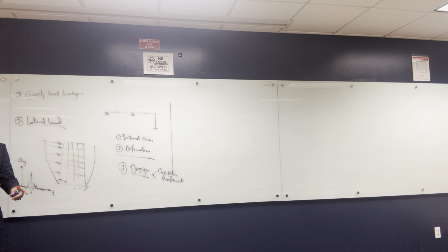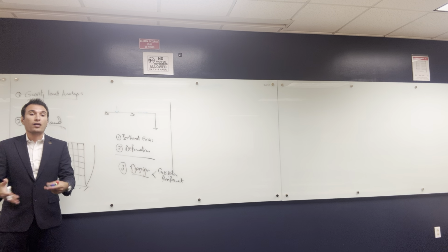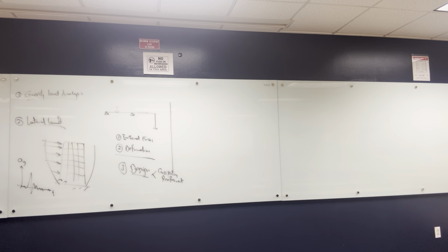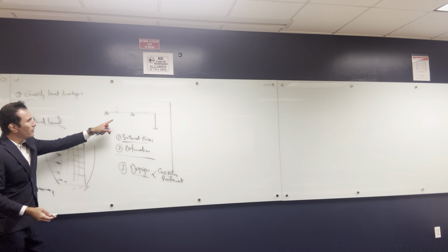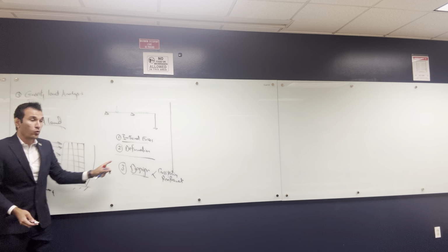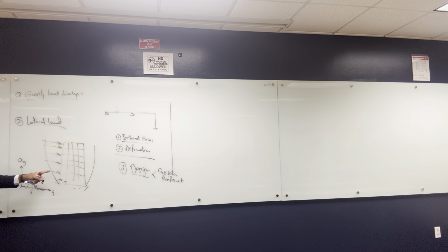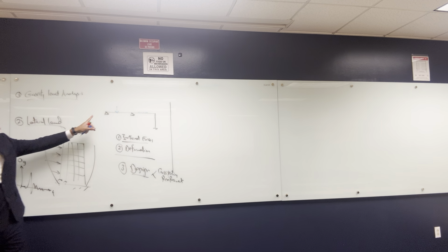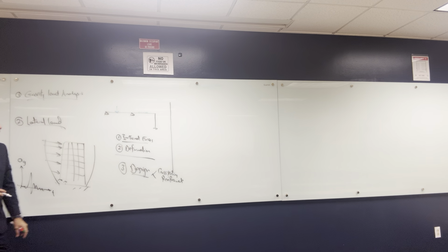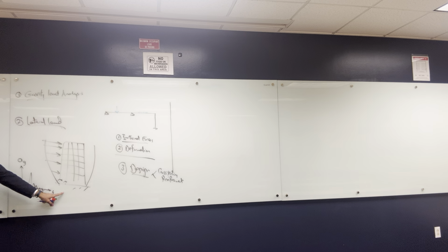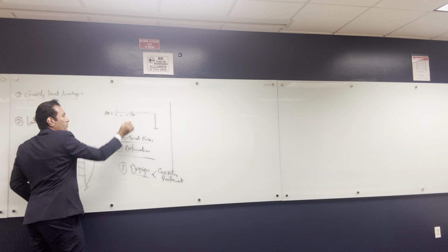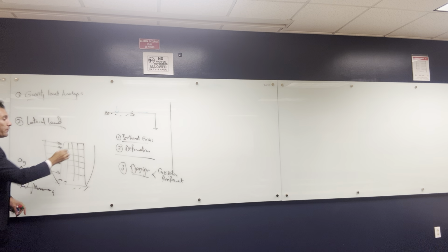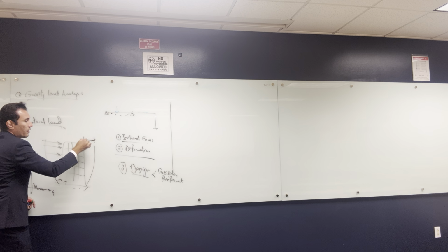We need to make the building comfortable to live in, okay? So it's the same thing, internal forces and deformation, but a little bit different from here. Here, for internal forces, we're looking at bending moments and shear forces in the columns and everything. Here we'll look at bending moments in the beams and the slabs. Deformation is the same thing here, but it's not deflection like what we used to. It's more like drift, the maximum drift the building does.